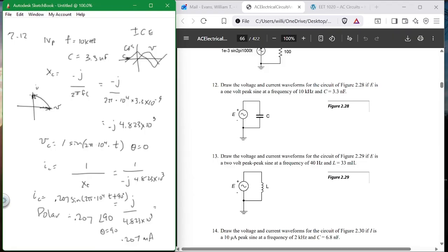So this is a dog race. And one is ahead of the other by a quarter of the way around. So a quarter of a lap. Okay? What do you think it is with an inductor? Just the opposite, right? ELI, E-L-I. Who's ahead in an inductive circuit? Voltage is ahead of current in an inductive circuit. So you will see the phase shift, but the other way. Here's voltage ahead of current. Here's current ahead of voltage with a capacitor. With a capacitor and an inductor, it's the exact opposite.